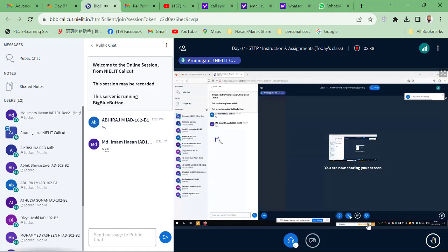Starting from M, it is memory, B means byte. MB0 means byte; next, if you want a word, you go to MW, MW1. Then MW1 contains MB1, and so on. After finishing this container, come to the next container.